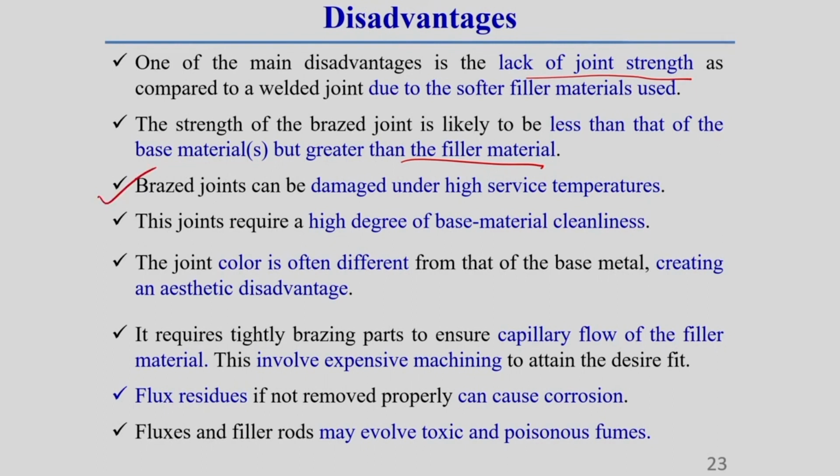Braze joints can be damaged under high service temperature, because if the braze component is used in high service conditions, there is a chance of damage to that brazing joint. These joints require a high degree of base material cleanliness. Why is this cleanliness required? I have already told you. Cleanliness improves wettability and improves the capillary action. That is why cleanliness is very much essential.